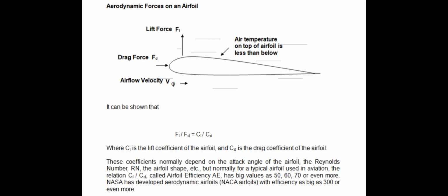Its value depends on the particular design of the airfoil and also on the collocation or placement of the airfoils around the periphery of the inner cylinder and the internal periphery of the outer cylinder. And given that the ratio CL over CD is large, the usable power generated by the lift force is generally much greater than the power consumed by the turbine due to the drag force.